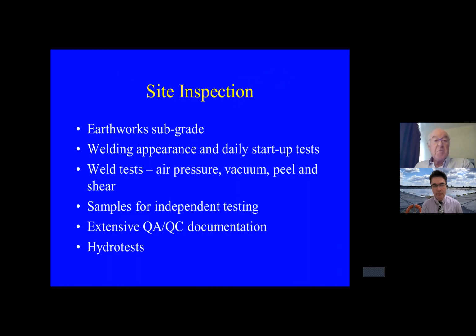The site inspection included all the normal things: earthworks, subgrade, welding appearance, and daily startup tests, weld tests, air pressure, vacuum tests. We did a huge amount of vacuum tests, more than you would normally see, and the normal peel and shear tests. And we took samples for independent testing. And there was very extensive QA/QC documentation. And then finally, we filled these tanks with water and carried out hydro tests on them.